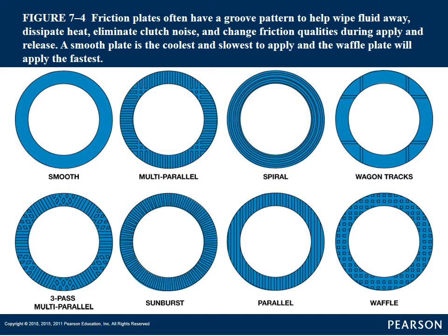You're not going to have necessarily control over this, because you're going to buy clutches that are designed for each clutch pack for each transmission, because there's no universal here. It's not like you can say, these clutches will fit all these transmissions, so I can just buy these clutch discs and put them in all these different transmissions. Most transmissions are going to use different clutch discs because they're designed specifically for that transmission.